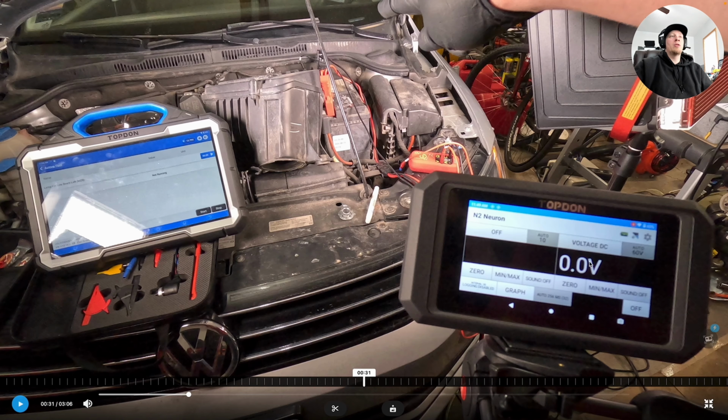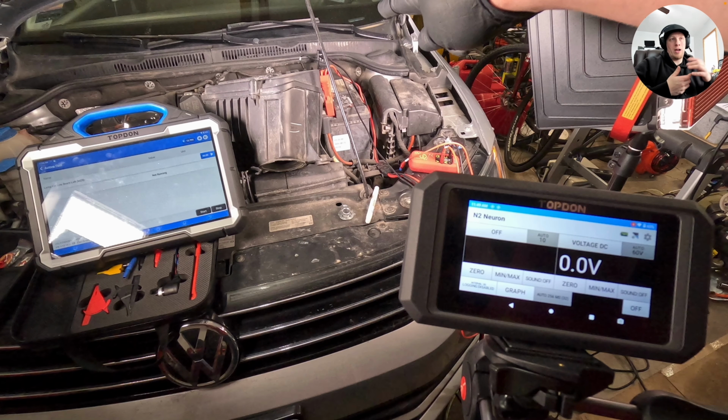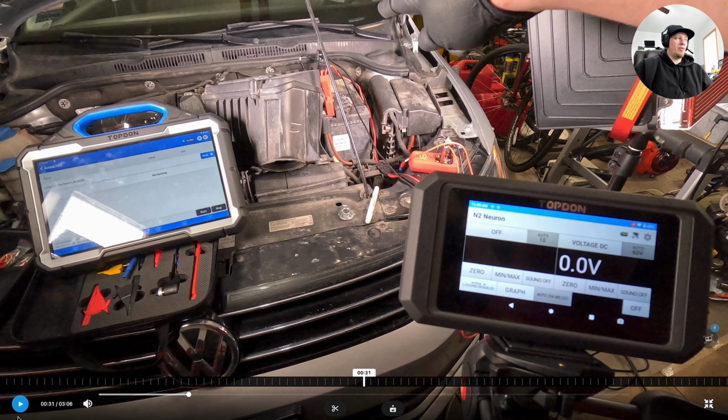We are measuring 0 volts. Now you're wondering, okay, what does that mean? We're measuring no voltage difference. There's no potential difference. It's essentially performing a subtraction. So what we have here is a difference of 0 volts, which means this is most likely a ground. Now we can't be 100% sure because if the circuit is not powered up, we may not be able to determine that right out of the gate. So we need to check the other pin first before we're sure what we're on.